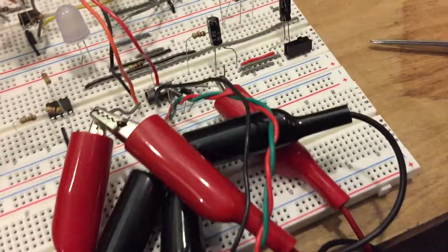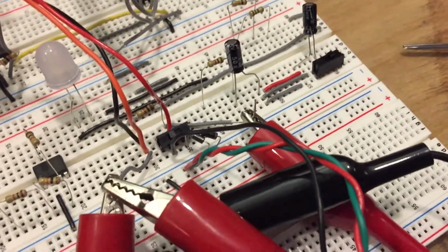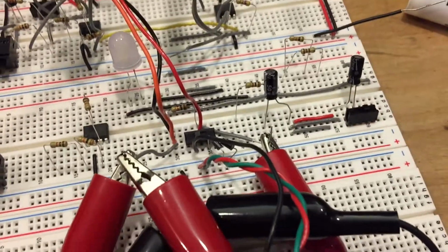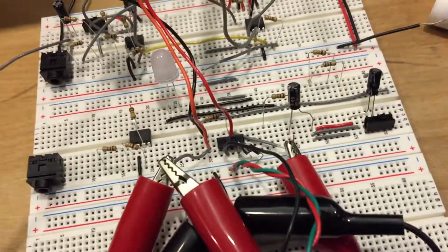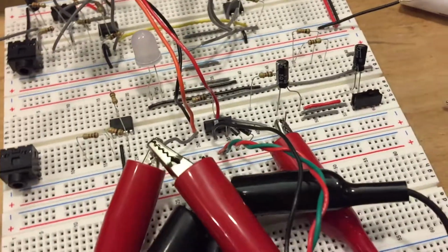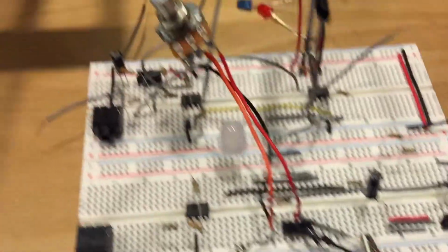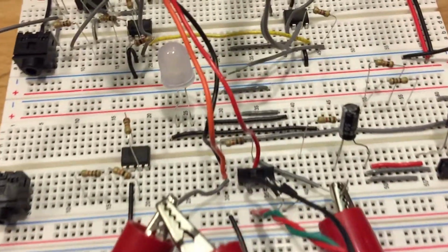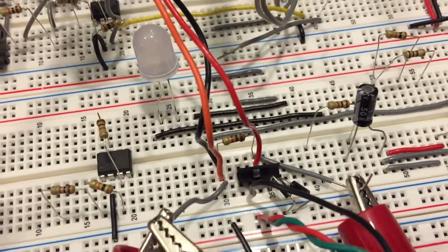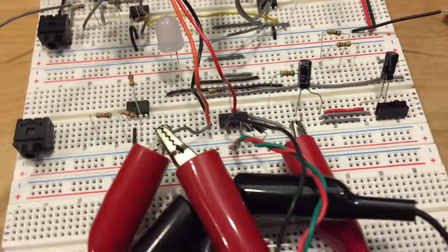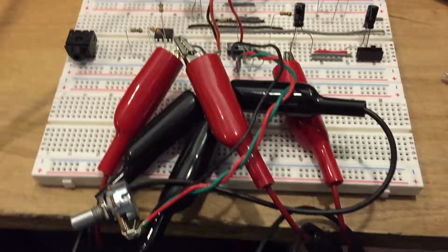But because this is a voltage divider and we want to maintain as much of the voltage as possible so that it is present at the output, we need a large resistor. Preferably, we want a resistor that's larger than our 10K here, which, because it's in parallel with another 10K right here, means that this could be as low as 5K.